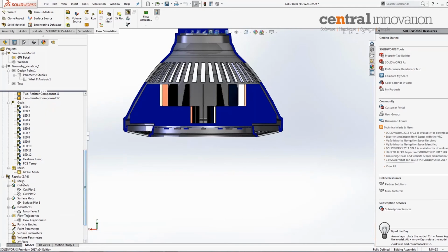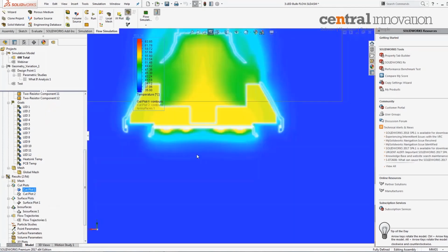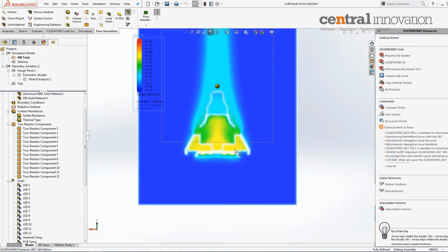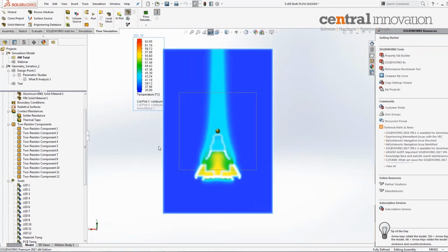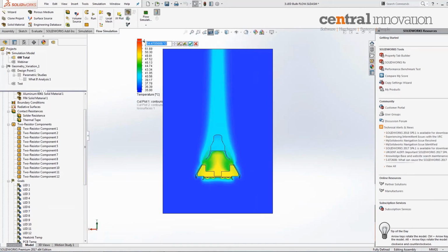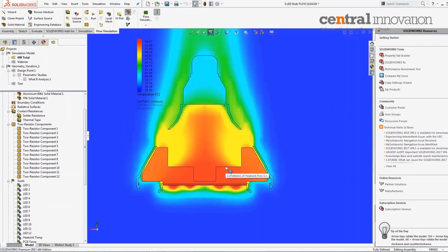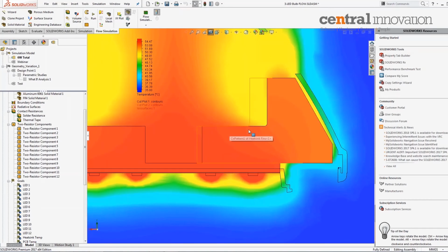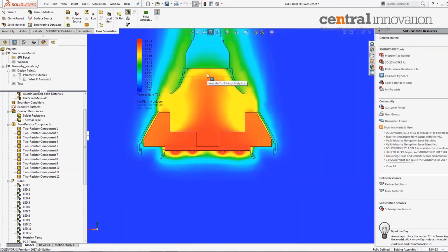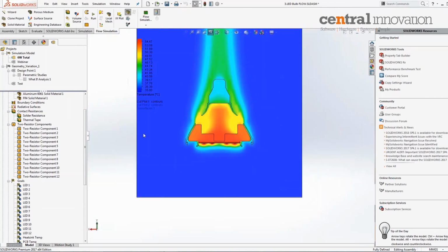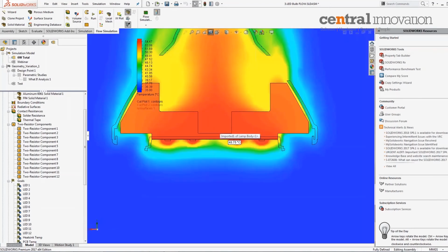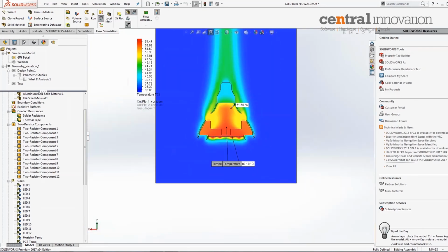We've added in here some cut plots. We're going to show one first. This one shows the convection model quite clearly. It's showing temperature in my model, and this can be slid down. Shows clearly the heat coming out through my heat sinks and creating this convection column up through here. We can use a probe tool in a similar fashion to actually probe the heat of my air in my model and on each of my entities.